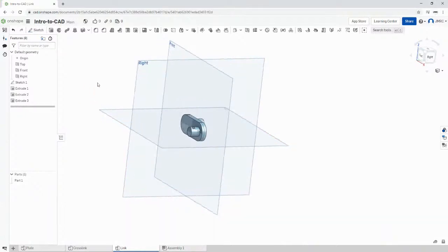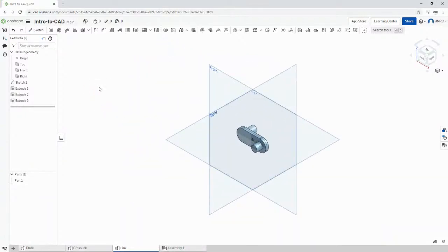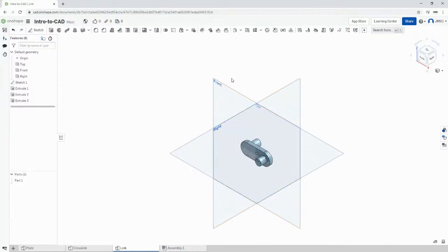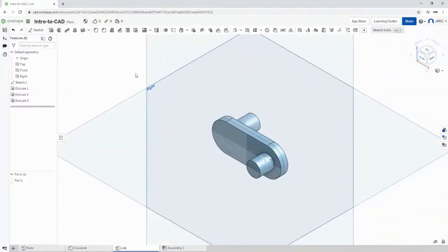Okay, so in addition, notice as I select this front plane, it's currently highlighted in orange. If you would like to deselect any specific item or feature, it's simply left clicking on the blank area of our graphics window. So I'm going to left click anywhere here to deselect. Okay, so that's for our young ones who are absolute beginners into the world of CAD.